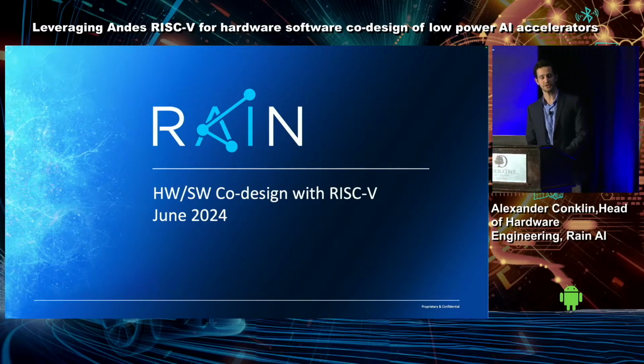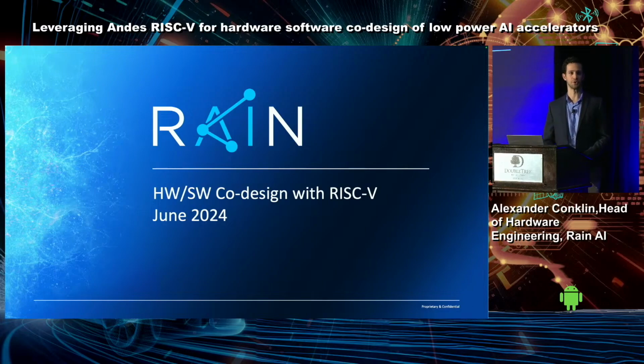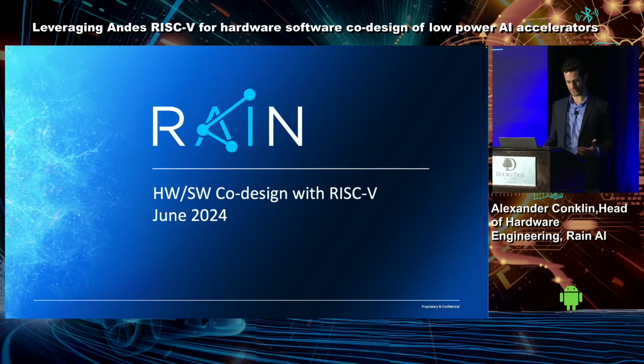The focus of this talk will be to showcase what we call a RISC-V-centric approach to AI accelerator development. And we'll talk about some of the challenges in building custom AI accelerators, especially with regards to the ISA and software. And we'll do this by walking through an example of how we might select some operators that we want to accelerate and how we integrate them into our architecture, the RISC-V extensions that we'll use to program them, and the benefits of preserving some of the RISC-V vector semantics.